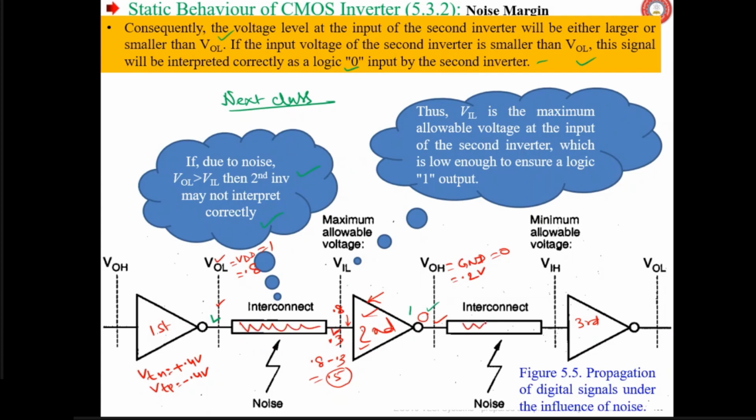There are a lot of problems in interconnect, especially nowadays, because earlier it was thicker and wider. Now due to scaling of the device, or technology scaling rather, not only device dimensions are reduced, but interconnects also have their width and thickness reduced.